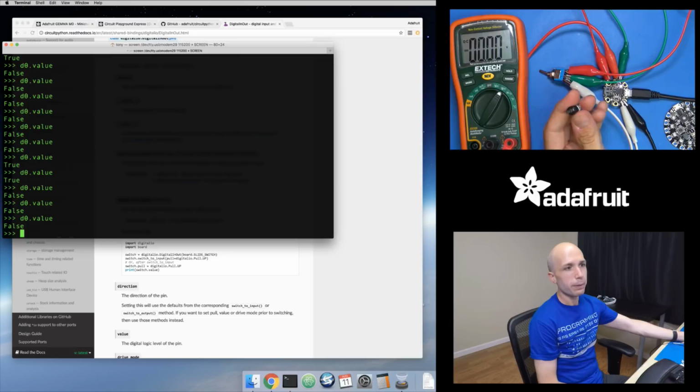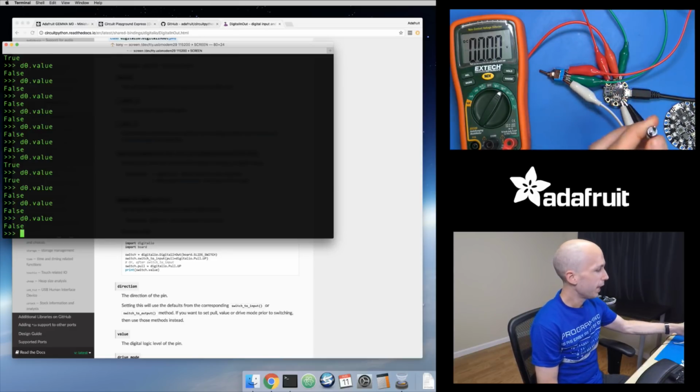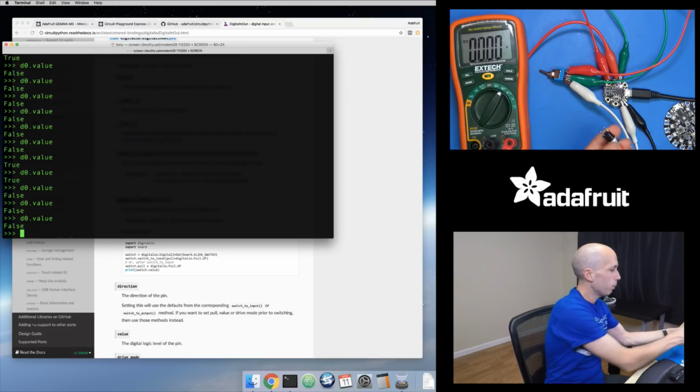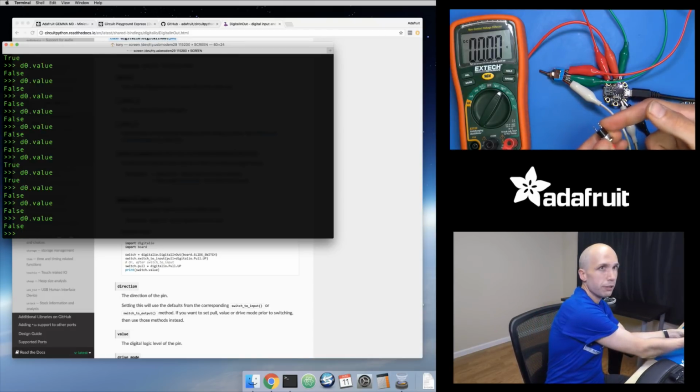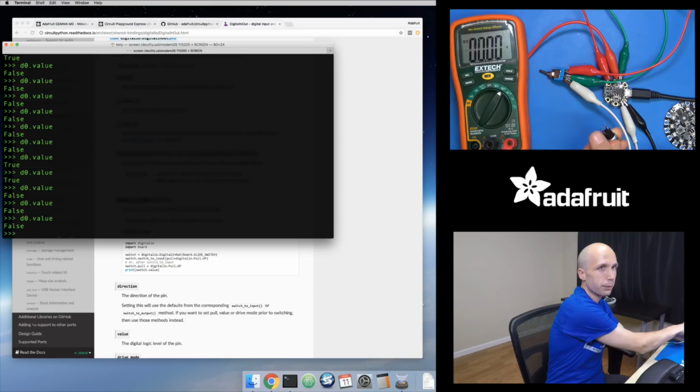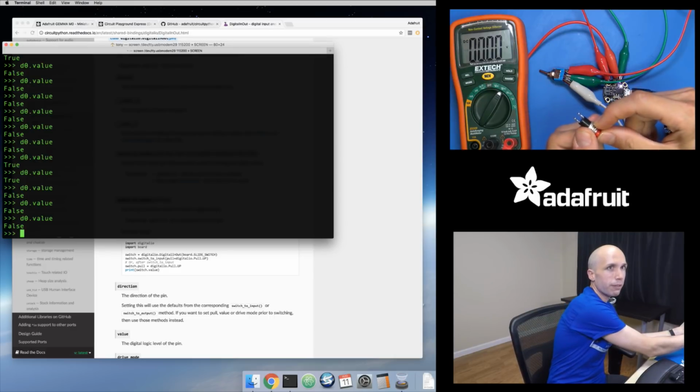And so you might be wondering, okay, how can I actually control this? How do I read this kind of a pin? I'll show you. We can set this up so that we connect our digital input to one of these pins on this switch, and then we connect either a ground or a 3.3 volt logic level to the other pin, so that when I press the button, it's going to connect them. Oops, sorry, so you can see this. When I press the button, it's going to make a physical connection between those two pins.